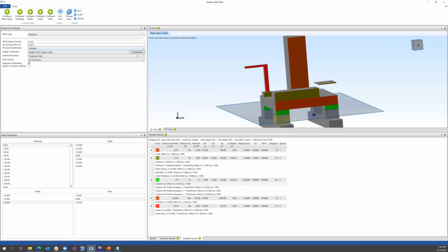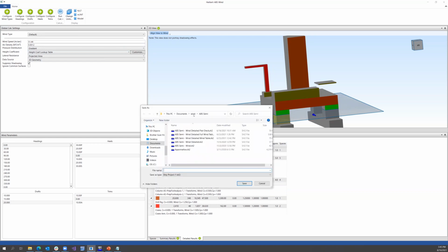And that is basically it for our wind analysis tool. What we can do from here is we can go up to File here, and we can actually save out this ship. And what it's going to do is update the wind table that we had shown previously as blank for this model with all of the results from our summary for all of these different vessel conditions.